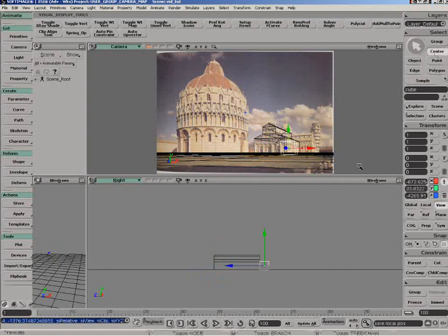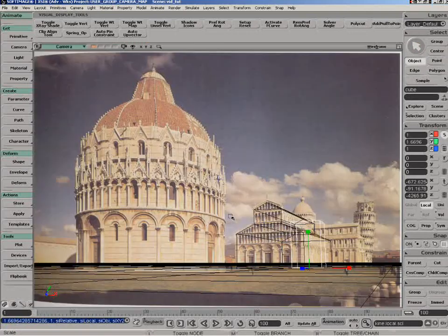Again, I'll make sure that the center pivot, I could just tag some points here and run center to vertices on it. That's probably going to be the easiest way. And then wherever I scale it from, again, it's going to be scaling from the ground up. I don't really need to worry about the X scaling at all. So there we go. We have something looking like that.